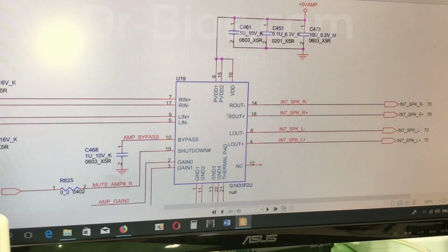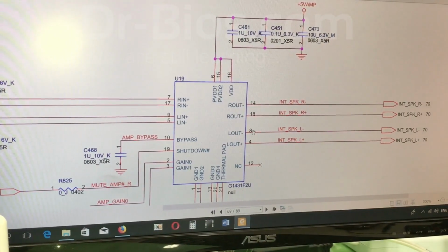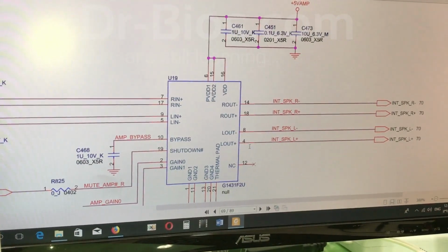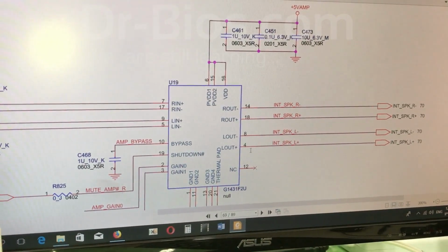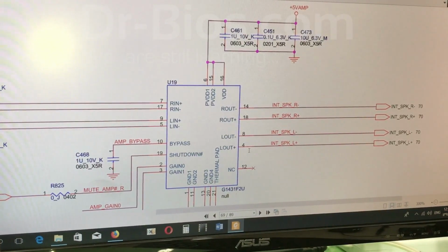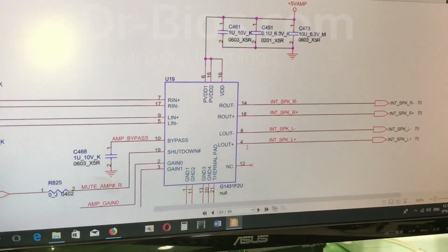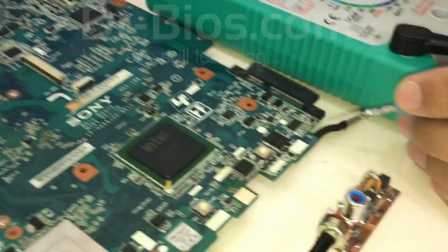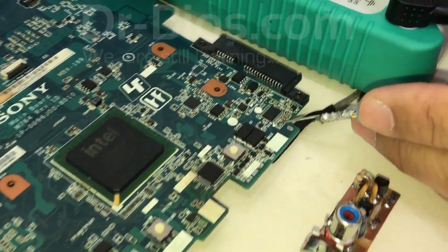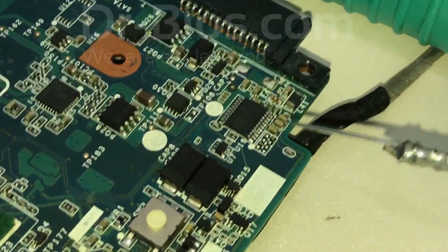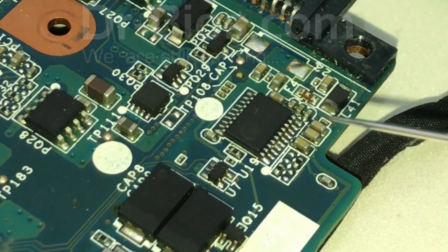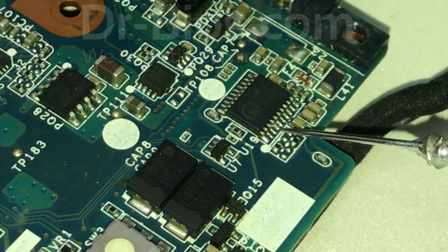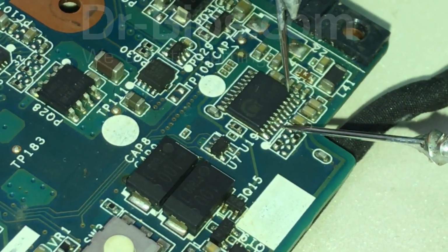The thing we did on the speaker, we could have done in here as well, meaning by placing the multimeter's probes on pins 8 and 4 of the amplifier IC. You can test the direction, connector and speaker. And you can test them by checking pins 14 and 18. This is pin 1. There is a mark on pin 1. Pin 4. Pins 5, 6, 7, 8.